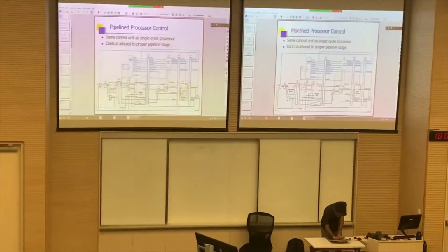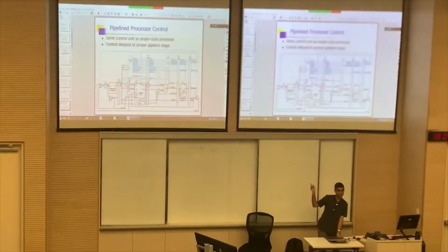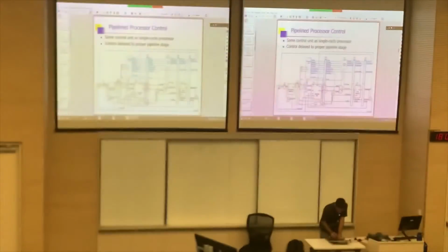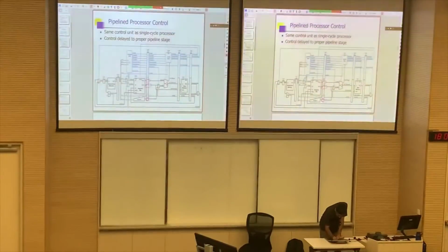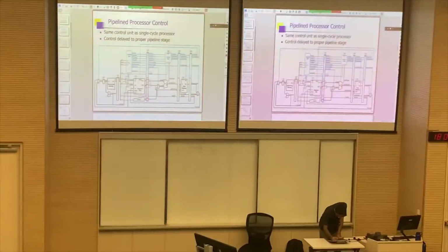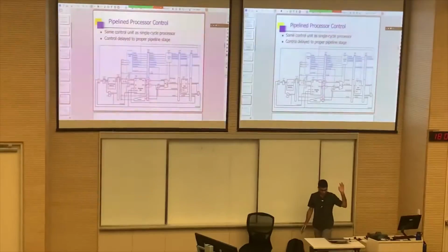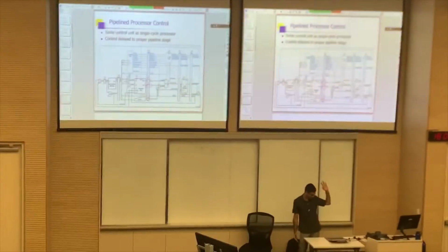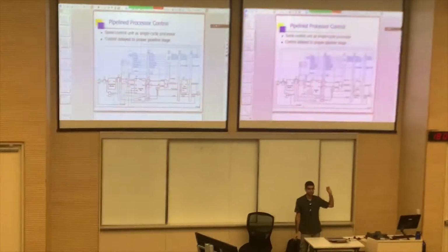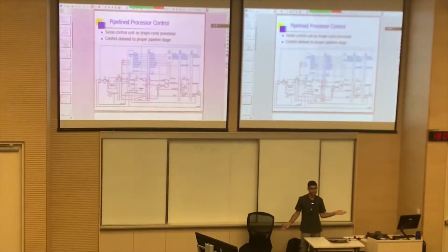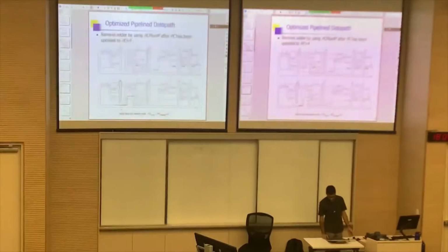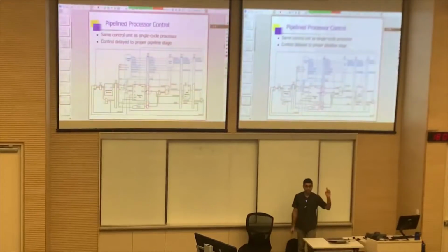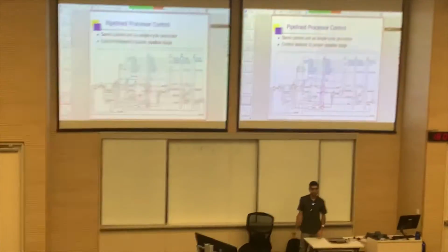So you see here in the E register you have this, that's already 32 bits, another 32 bits, another 32 bits, then there is a 4-bit value here, and then there are all these bits. Some of them are single bits, some of them are 2 bits. So it stores over 100 different bits, and that's a lot of hardware. And is that it? This is a pipeline without any hazard resolution mechanism.